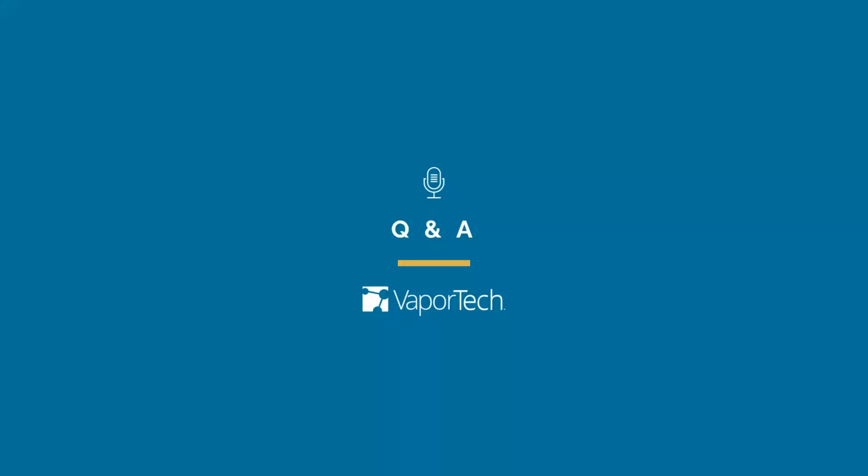Next question is, chrome oxide has poor adhesion compared with pure chrome on the metal substrate. Why? Well, it depends on the compatibility of the substrate material that you have with the coating that you're trying to put on top of it. So chrome oxide by itself is a very stable material. Oxides in general are very stable. So maybe it doesn't want to adhere to the substrate that you're putting it on.